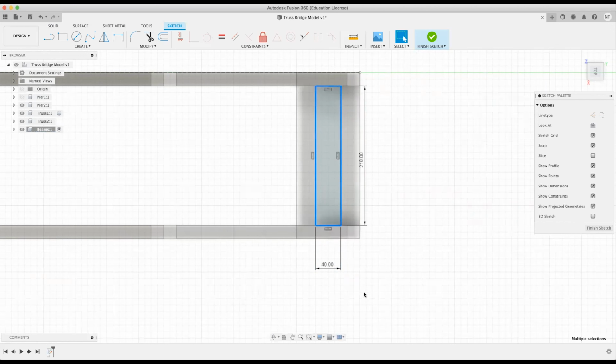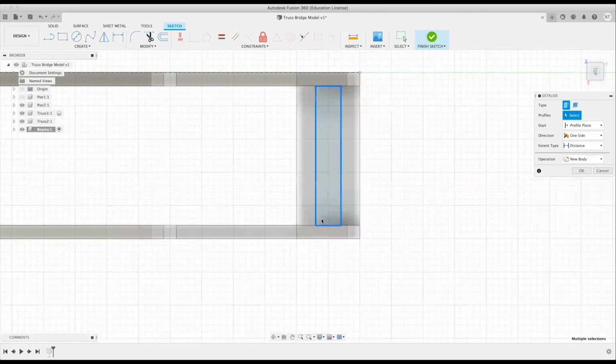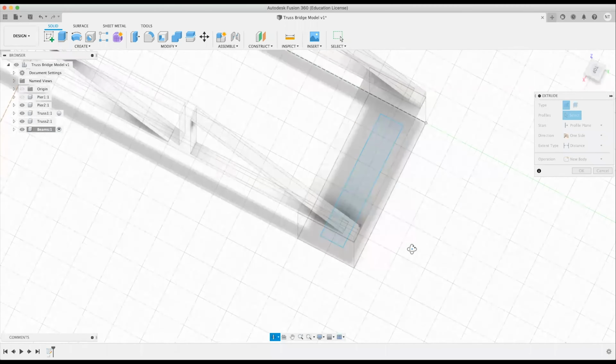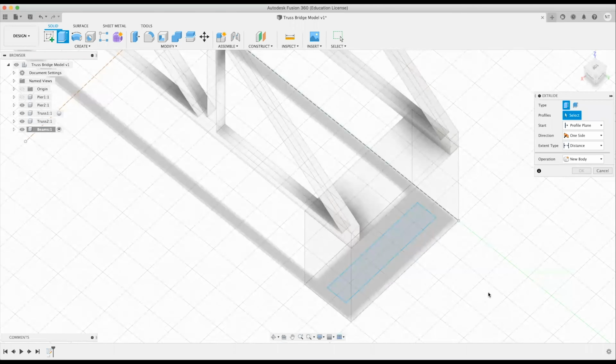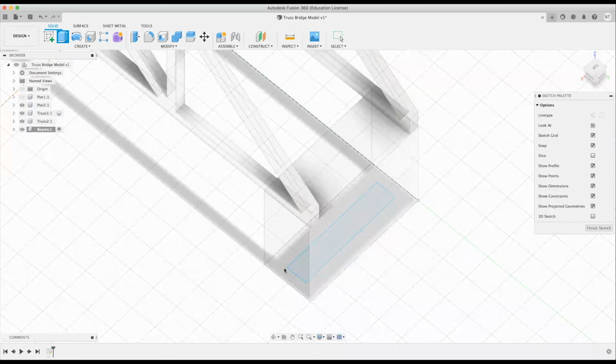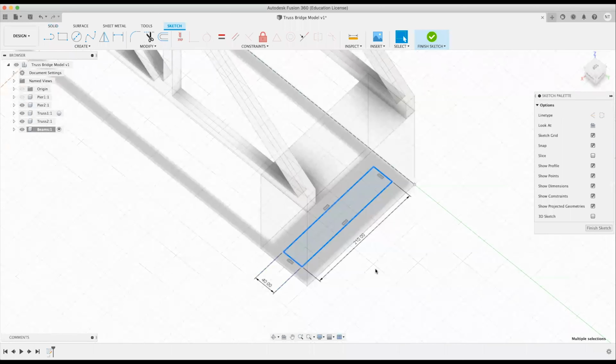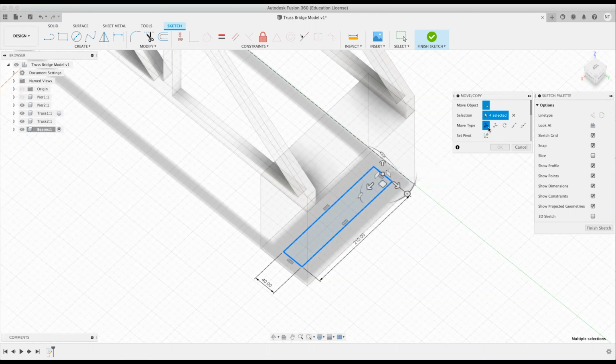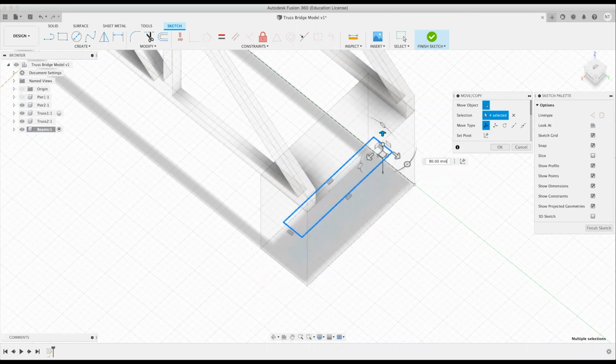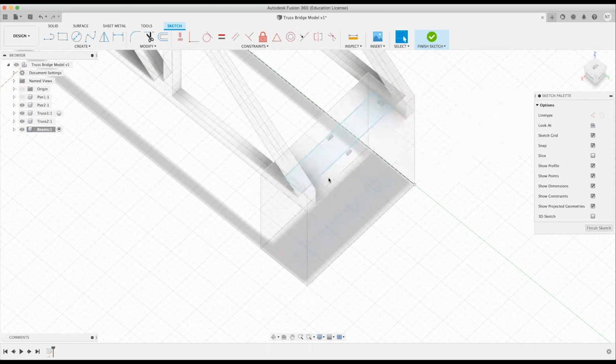And now we want to add a thickness to it. And since we have the frame ready, we'll hit E to extrude. So we actually have to move this sketch up a little, and that's okay. We'll use the free move command again, and we'll move it up 200 millimeters, so it's flush on the face of this abutment. Now we're ready to extrude.